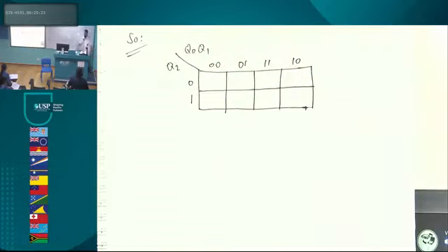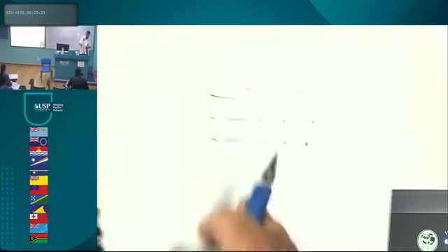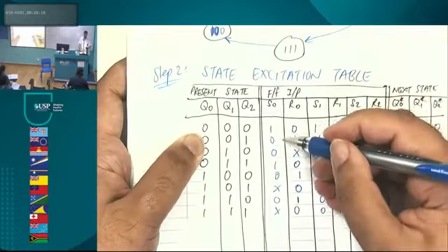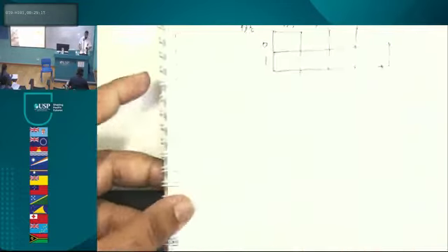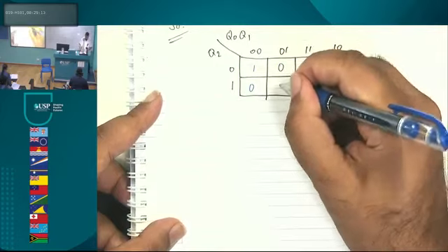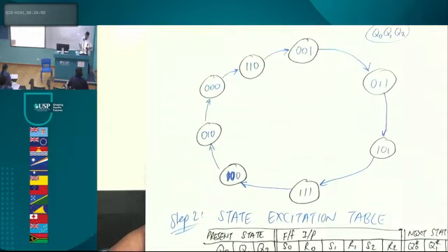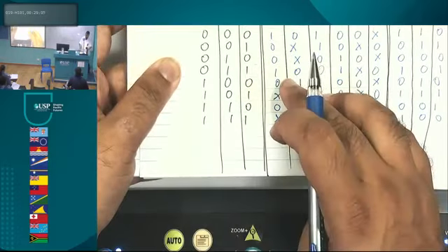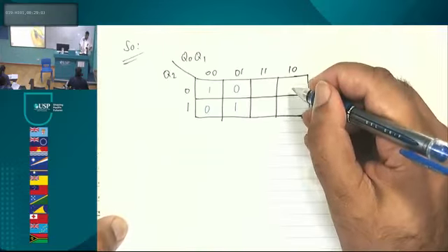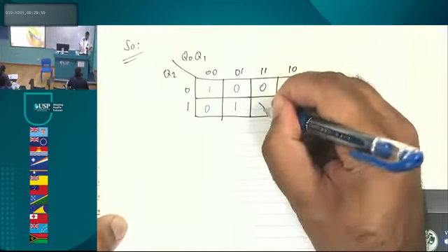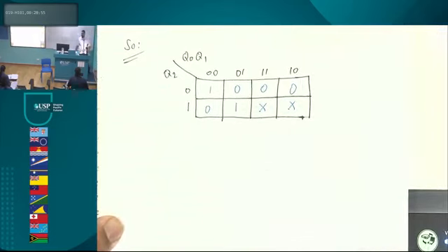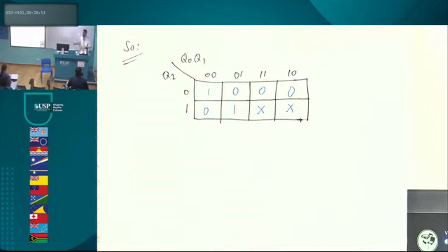I like to do it so that it's very easy for me to copy. Now, can you call out this? Look at this: 1, 0, 0, 1. Right, 1, 0, 0, 1. 0x, 0x. Look at this. I come here. You have to know the sequence. 0x, 0x. Set? You see how I did that? I filled it up, because now you should be a pro at Karnaugh maps. You should know which cell is where.